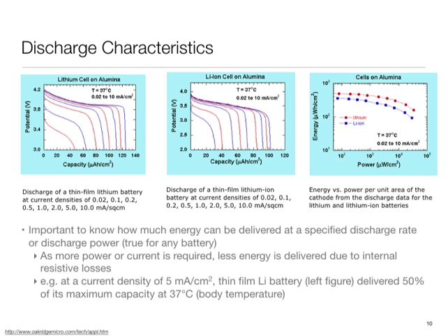But this is showing the following: that at a particular temperature, this left plot, for different amounts of current, that's the 0.02 to 10 milliamp per centimeter square, I achieve different amounts of capacity. So what's happening out here is I start the battery fully charged, and then as I discharge it, the voltage falls, and at some stage the voltage reaches some sort of a cutoff voltage, at which we consider the battery to be no longer sufficient.